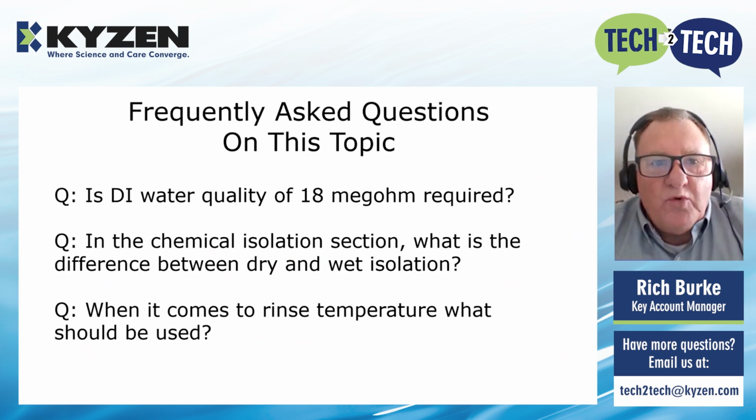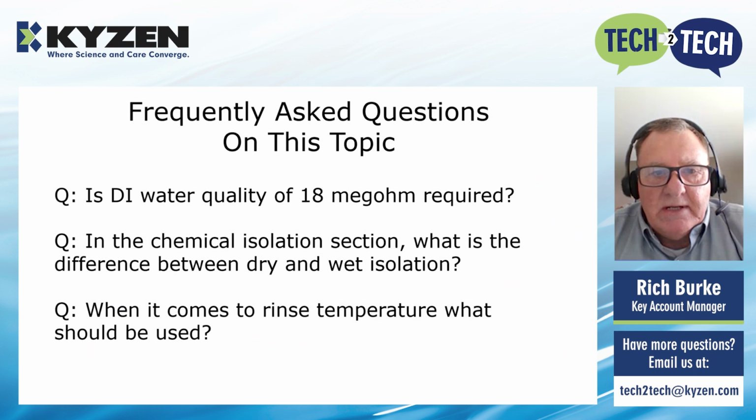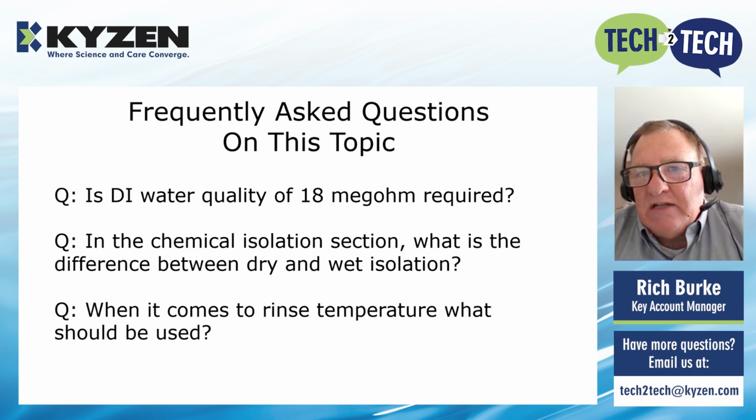Wrap up with a few frequently asked questions. The first one is: is DI water quality of 18 megohm required? Well, you've heard me mention 18 megohm, I think, a couple different times. It's not required. It's typically going to be what is realized when we come out of mixed bed systems.